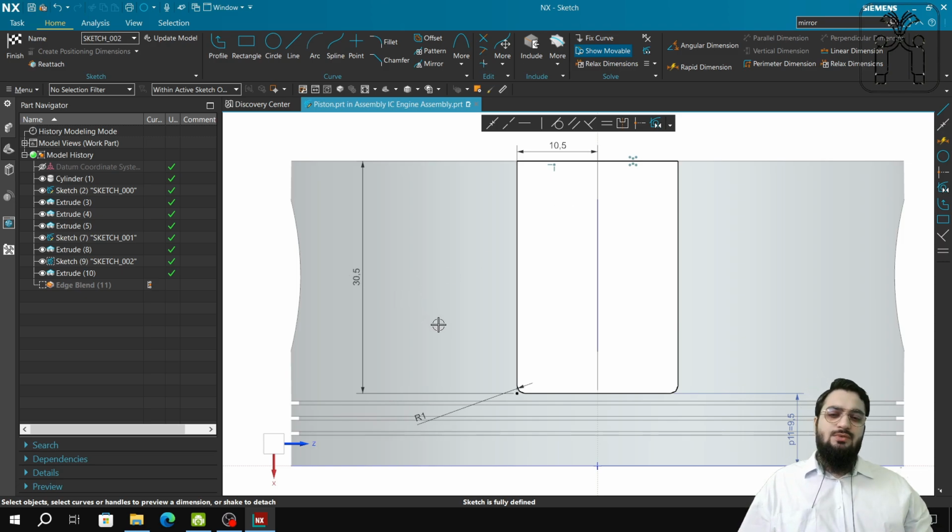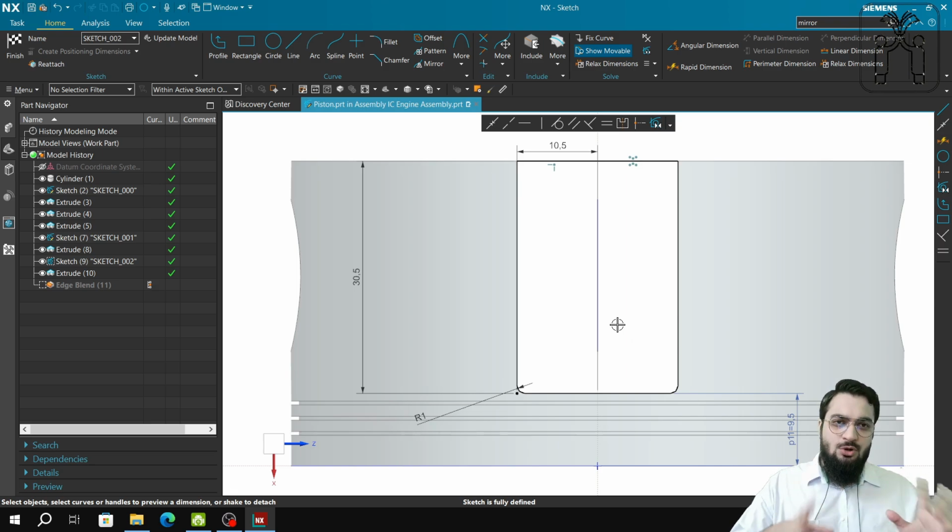After that, 30.5 mm is over here, because 20 mm is this hole, and this is 5 mm, and this is 5 mm. This is 30 mm. I took 0.5 because you are not able to see whether the connecting rod is getting inside the piston. No, it was not getting inside, it was barely touching. So I made it 0.5 so that you can have a certain gap between them, so it looks good in an animation. And this is 9.5 because 40 minus 30.5 is 9.5.